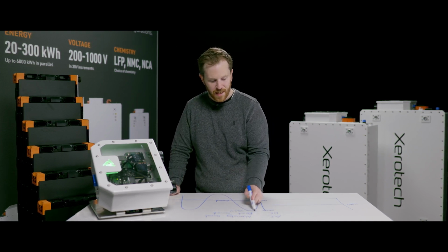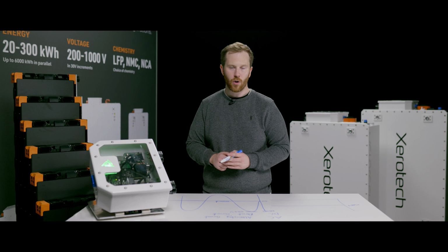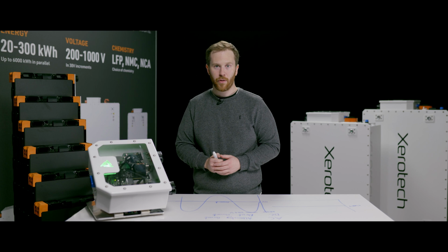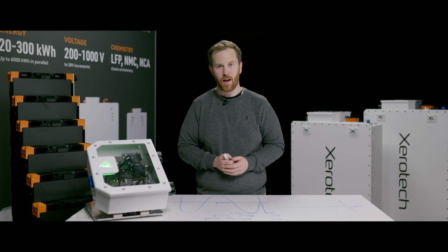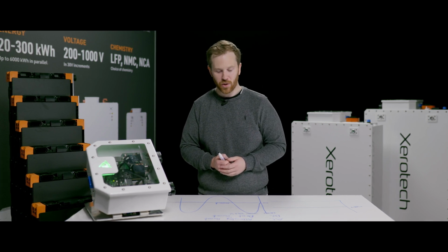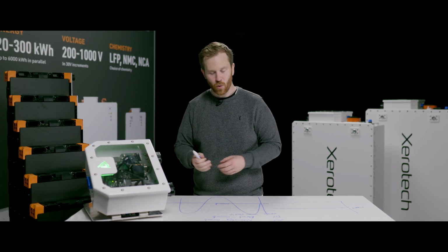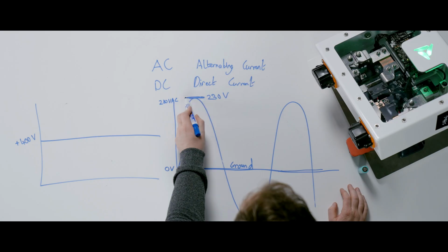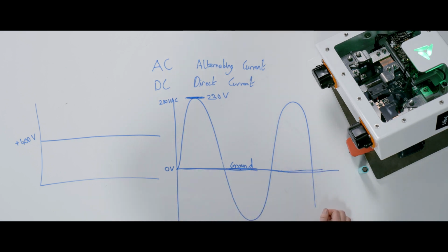So that means that for an AC power circuit, you're always touching the other side of the circuit. You're always touching the neutral wire or the ground wire effectively by being on the ground. So that means that if you've probably been told as a child, or hopefully as an adult, to never touch a live wire because you'll get electrocuted, you get shocked. And the reason is you're always in contact with the second wire. So when you touch the live wire, you complete that circuit and you're experiencing a potential difference between the live wire and ground.